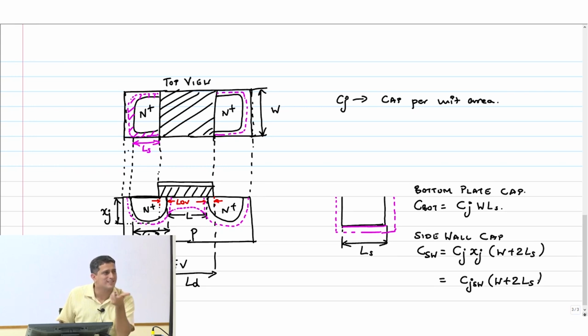Channel length is under the channel. It only depends on the width. So again we are going to do the same trick. We are going to split this as technology constant multiplied with some design parameter. Design parameter here is only W. L is not available here, even for analog guys.